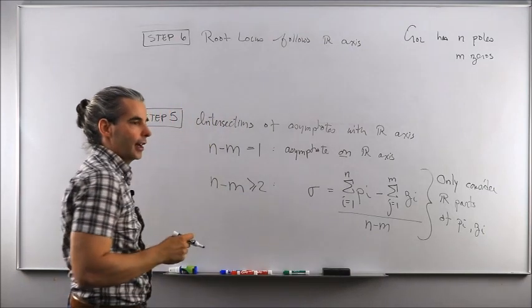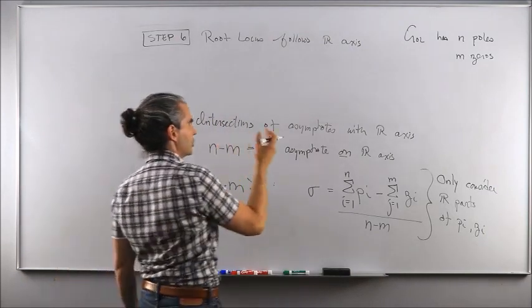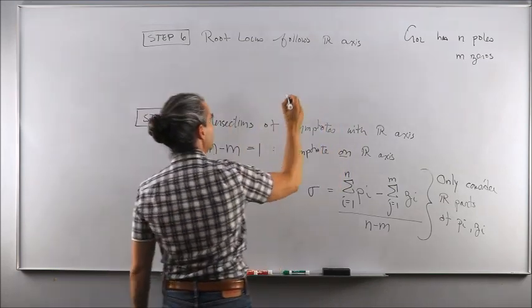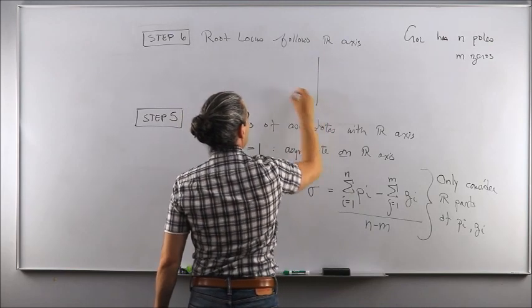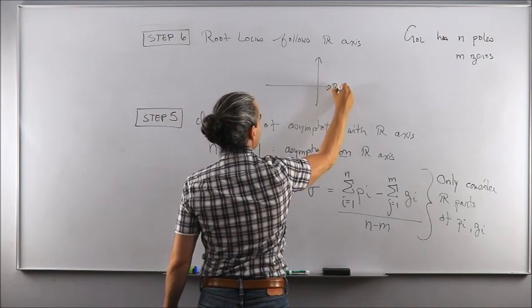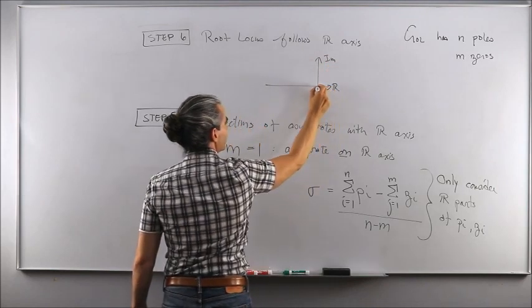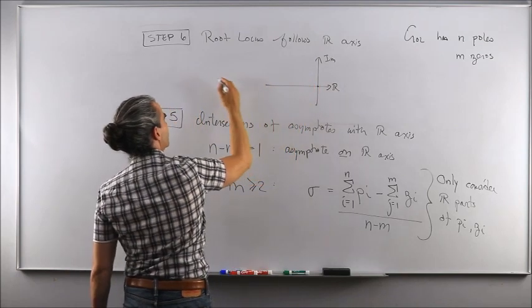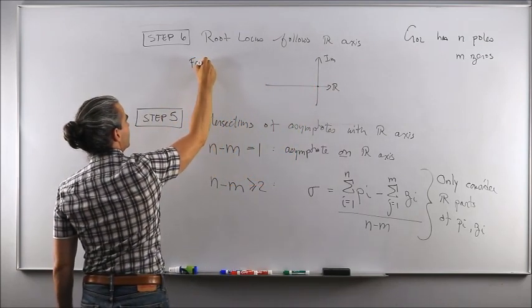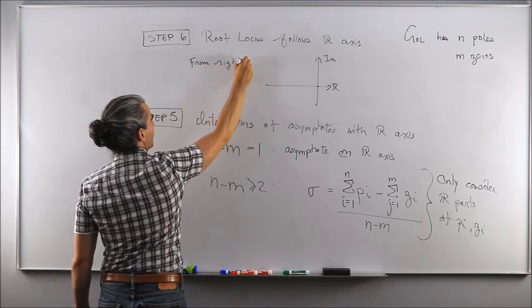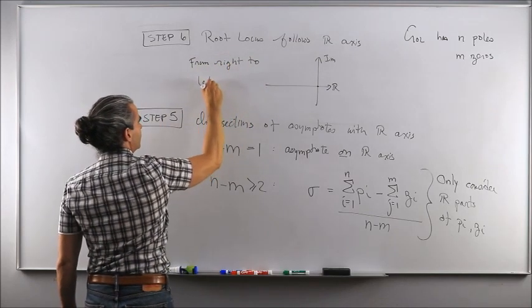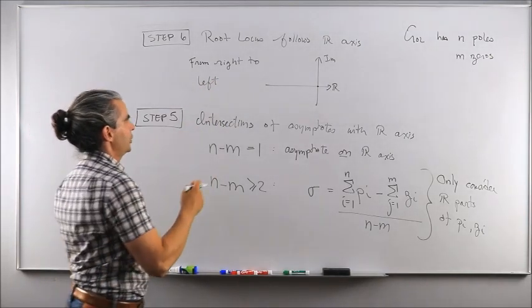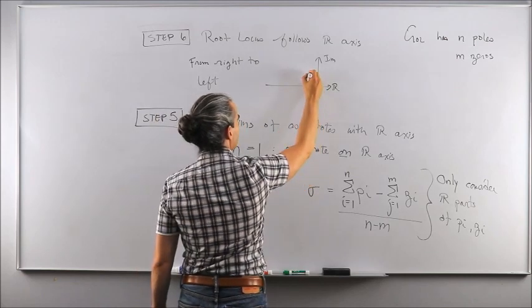And for this, it's not an equation, it's just from visualization of all the poles and zeros you had placed in the root locus. You need to count. So the way that we count is that we start at the origin here, and we count by moving to the left, from right to left. Okay? What do you count? Well, you count everything you encounter.